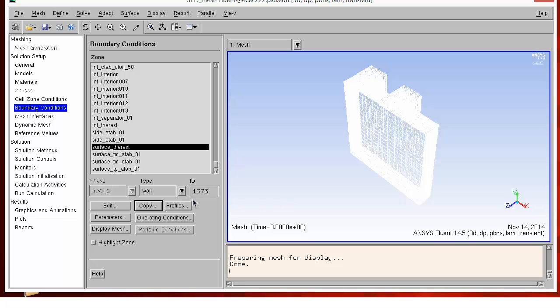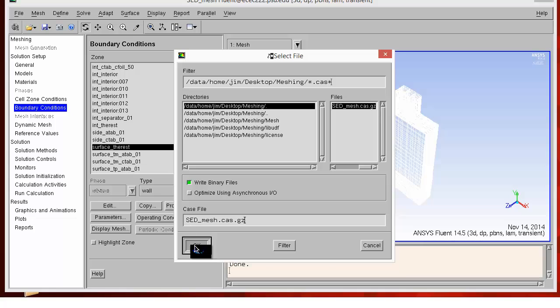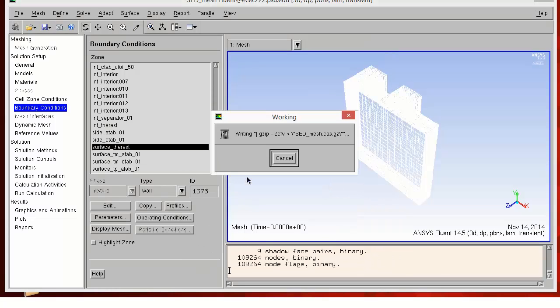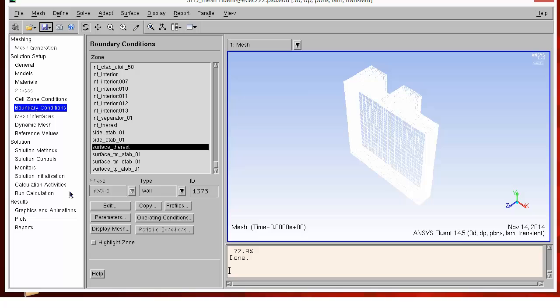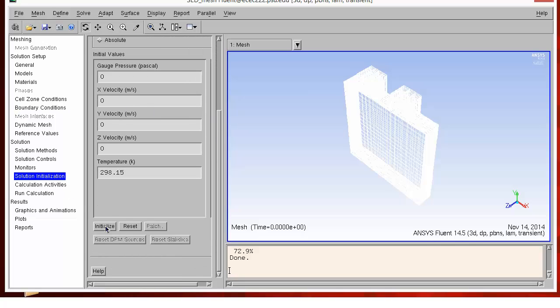Once this is done, we can initialize the simulation by setting the ambient temperature and, if desired, the type of output files from Fluent. We can initialize the simulation, confirm the operating conditions are correct, and then run the simulation.